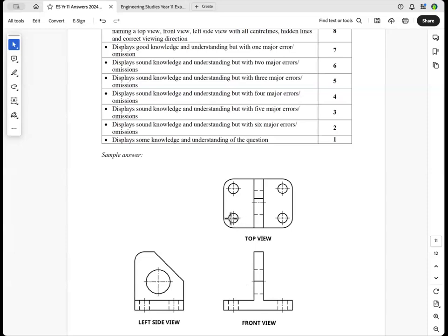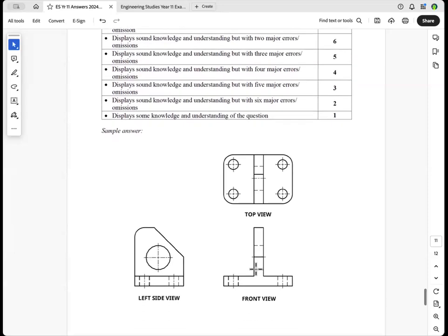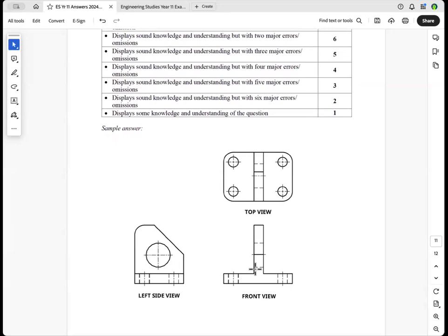With these circles here, you've got to put your center lines. Here's a circle here. A lot of you missed out these hidden detail lines here. There's your center for the circle. Make sure that you're consistent down here. See that change produces a line, and that goes across there. And I was checking to see that your projections were right. This top of the circle has to be in line with that there. And so that's an orthogonal drawing from a pictorial drawing.